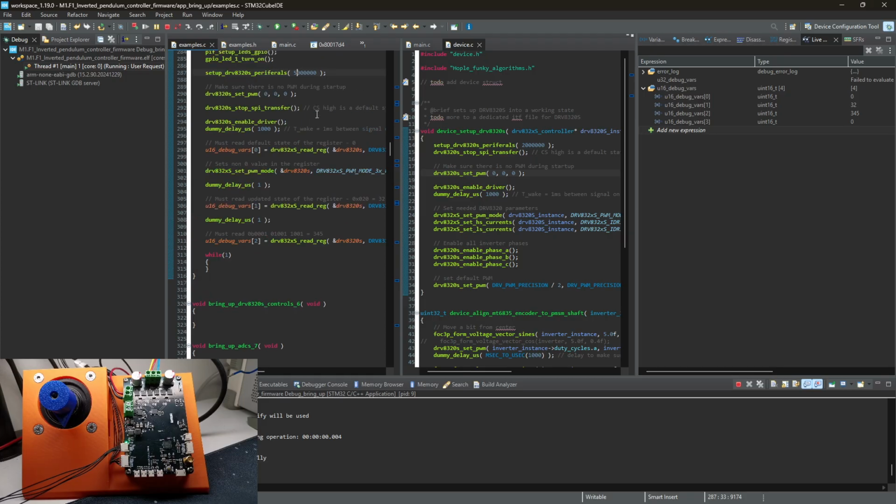Oh, I remember now why I put 2 million. Oh, I do remember. It's an electronics issue. Because of my tracing of the PCB, I imagine the SPI lines had very terrible signal shape, so I had to lower the communication speed so that the signal has a proper shape that can be recognized by the IC.